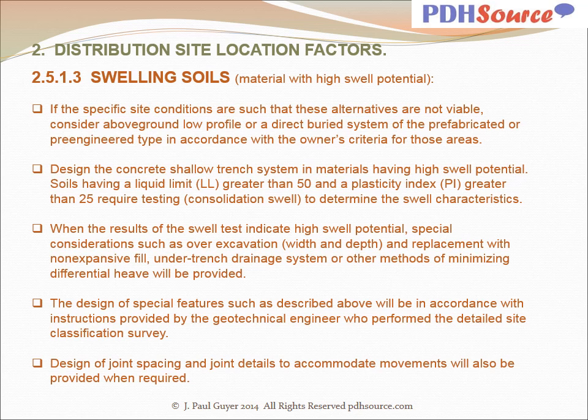Soils having a liquid limit greater than 50 and a plasticity index greater than 25 require testing for consolidation swell to determine the swell characteristics. When the results of the swell test indicate high swell potential, special considerations such as over-excavation, width and depth, and replacement with non-expansive fill, under trench drainage system, or other methods of minimizing differential heave will be provided.